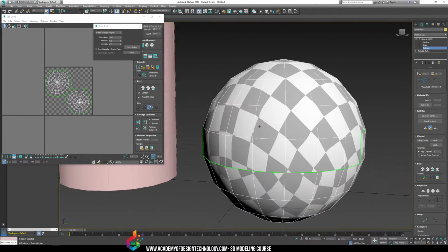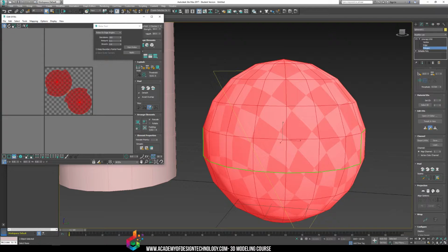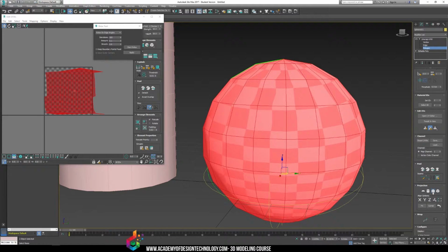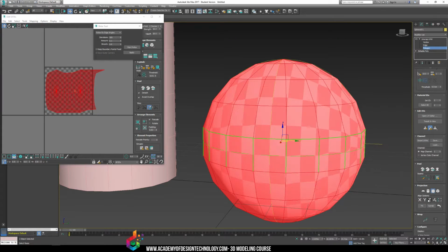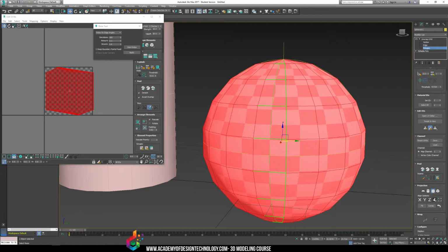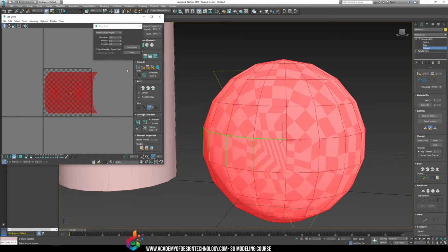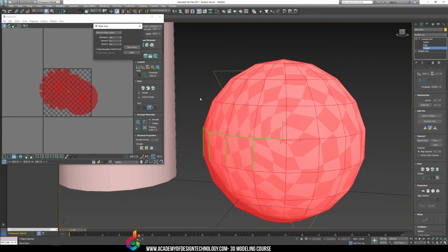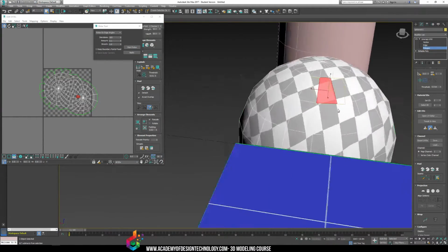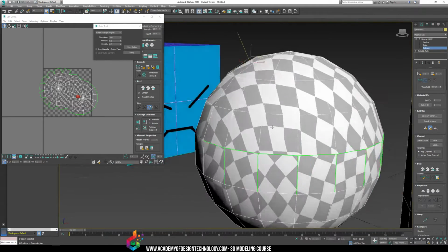Now, I can grab both of these and just go to projection, sphere. And I can go to best alignment for the projection of a sphere. And you can see that it's a little bit tricky trying to align this. I'm going to align it on the X, Y, Z. I'm going to start to relax. And you can see that the relaxation is a lot different than the actual model. There's a lot more curves to it. Everything looks a little bit weird.